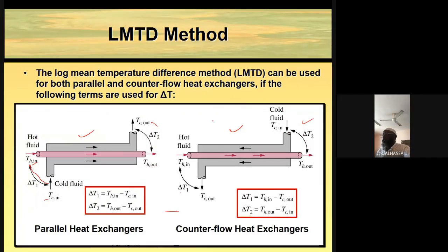So if I want to find any heat transfer for geometries like this, I would simply use Q equals UA delta T_m. But what if you have two shells or two tubes, four tubes, and so on like this? Now we need to introduce a new parameter called the correction factor.